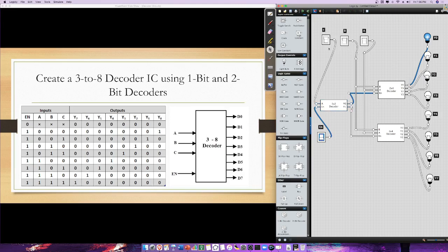Okay, now let's change this to this IC. Take note, I am not changing the values of A and B. So now I will select Y1 in my 1x2 decoder. This time, Y4 is turned on because now this IC is selected.